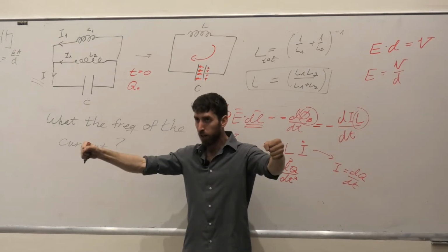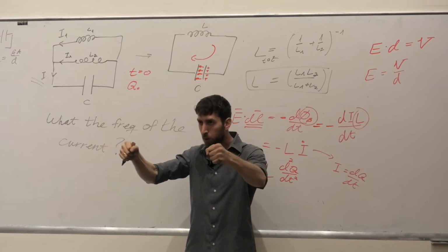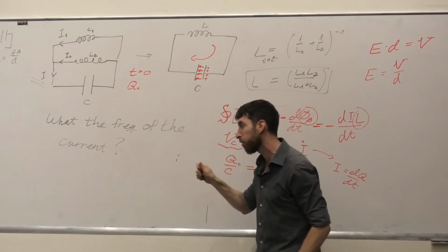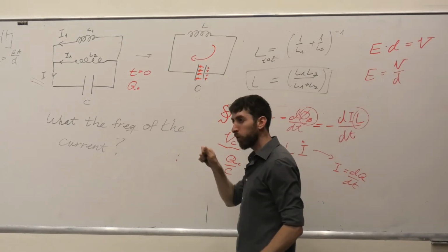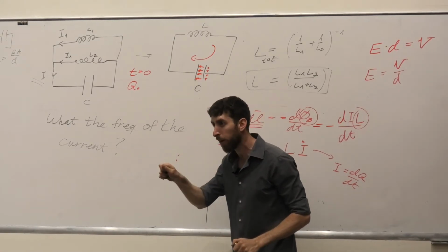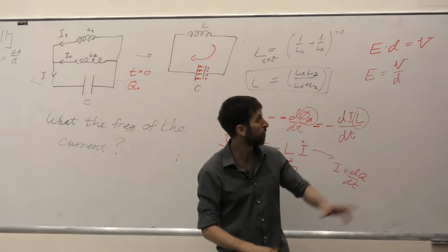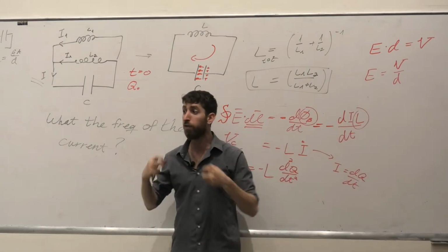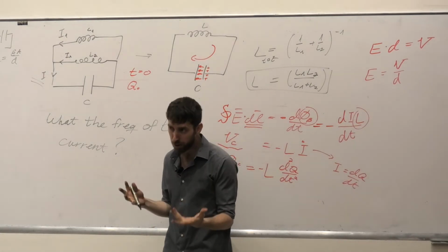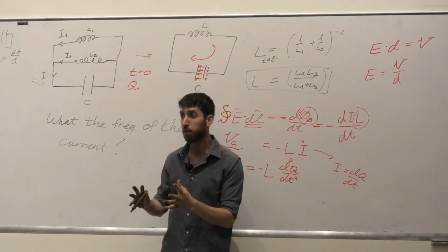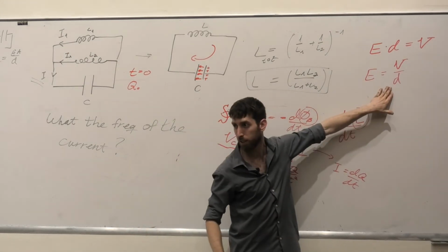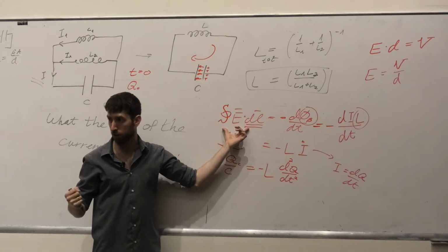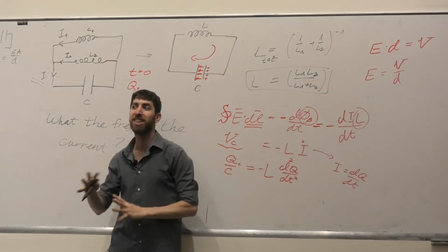When I put two wires really, really close, I'm going to see sparking. When you plug something into the wall, you sometimes see some light. This is the concept. So remember that electric field is volts, which represent energy divided by charge, per some distance. So this integral actually tells you to sum up the voltages in the circuit, in a more precise way.